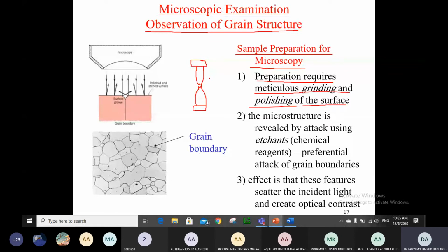Now, in terms of seeing what the microstructure is, you can sample from here, but if you sample from here, the material would have the form. So this is after going through plastic deformation. Normally in our machine there, the loading is done on the shoulders here. So the shoulders, the grip looks like that, sorry for drawing this like that. So the load is applied there. So basically this part of the specimen does not go through any deformation, and that's why we normally cut from here and see what the original microstructure looks like.